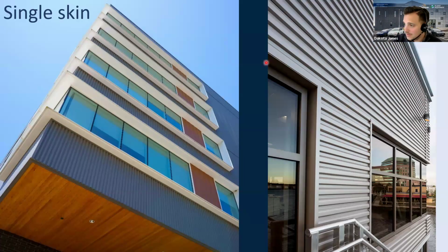The other thing you'll notice too, look at this corner. Those are exposed teeth. There's no trim on that corner for a corrugated panel. Look at this trim, right? What we can do is miter the inside of that insulated metal panel and then bend it 90 degrees in order to wrap a corner and have that insulation on insulation connection. Something that is pretty neat and can be done even with a corrugated panel. You just gotta ask.